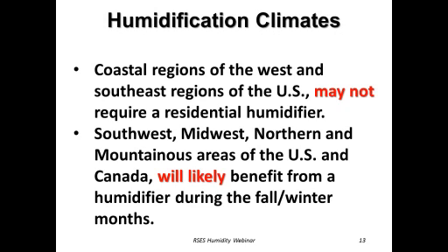But keep in mind that a lot of new construction, especially new construction that is wood framed, does not require a humidifier, because newer buildings are built so tight, and the amount of moisture produced simply from living or working in the space might produce enough humidity to keep the conditioned space comfortable.